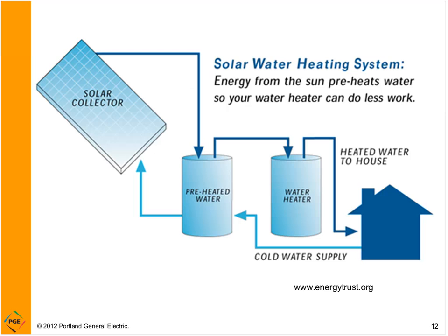Basically, the point of using solar thermal to heat water is that incoming water temperature is very cold. So your cold water supply is typically in the range of 40 to 50 degrees Fahrenheit. You typically use water at 110, 120, sometimes 130 degrees Fahrenheit. To get the water from that cold incoming temperature to your desired outlet temperature takes a lot of energy.